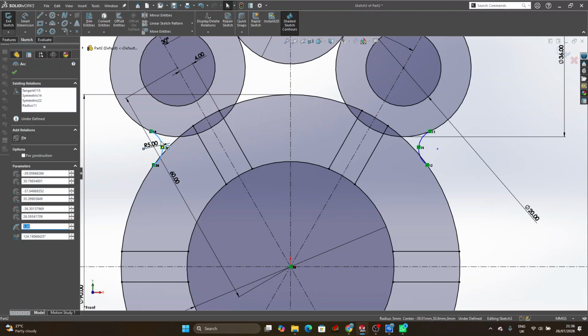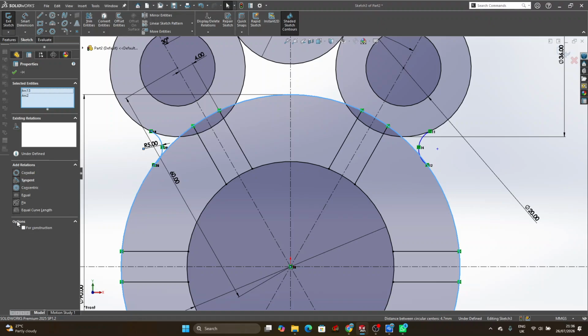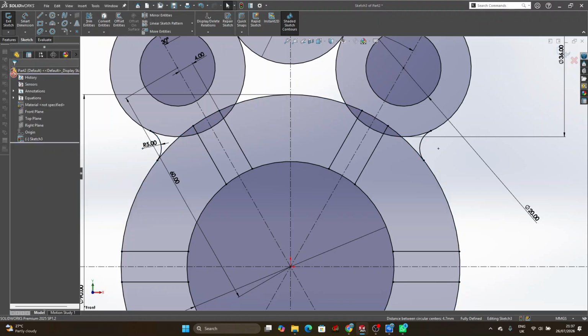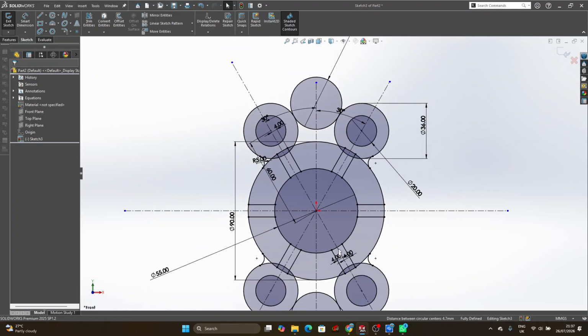That one is under 3D. I will explain those parts. We are still in 2D now. As I'm clicking on this, the children are also updating to reflect the change I did. Still holding my Control key, click on this circle. I'm making it tangent again. The child just obeyed the parent. Can you see? It's already black. This is what you need.